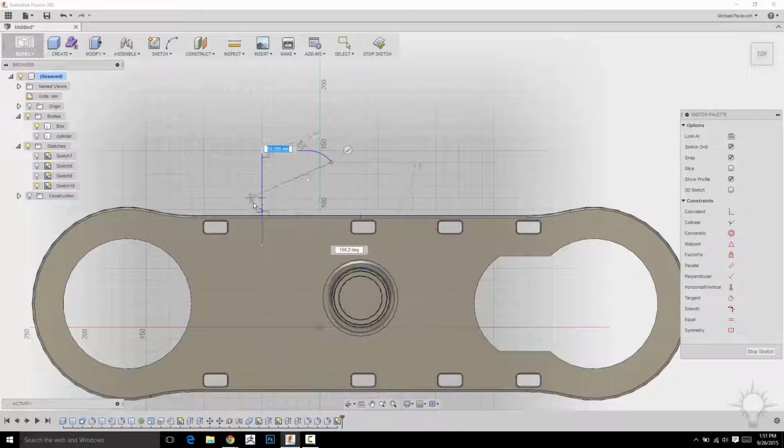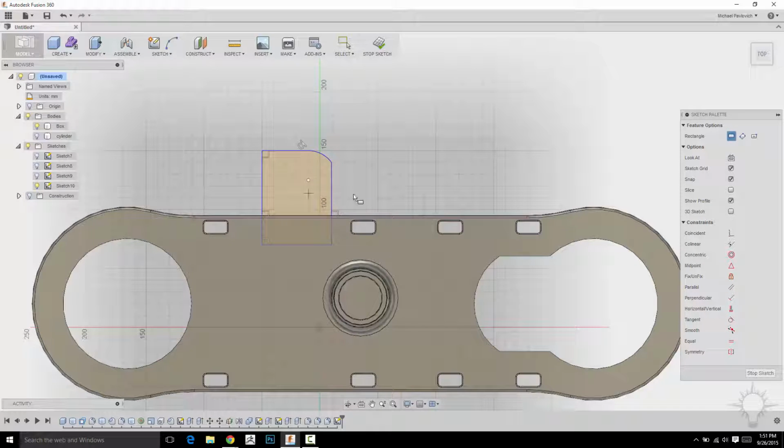And if I want to make sure I'm exactly to the bottom of this point, I can select that, or not select it, hover. It'll hover select it for me, and then I'm going to go to the right here, and it's going to make that blue line, and then I know when I click here and then click here, it'll go ahead and make that closed shape for me. Now at this point I can hit R, and that'll make a rectangle. If I want to take a chunk out of this, I can.